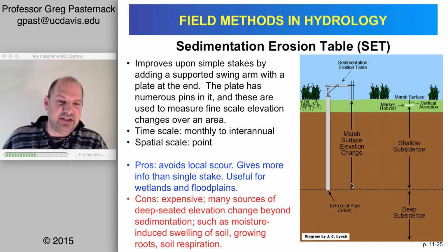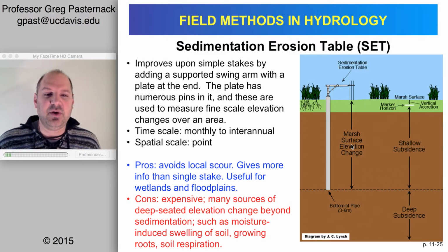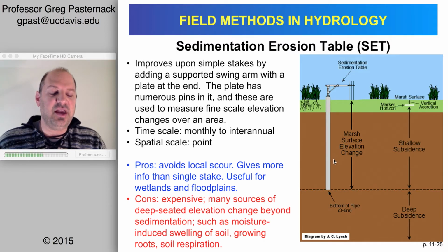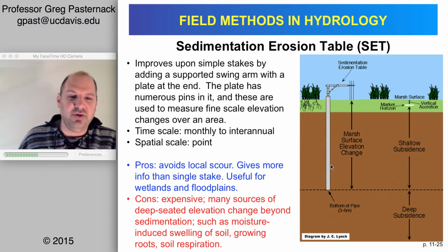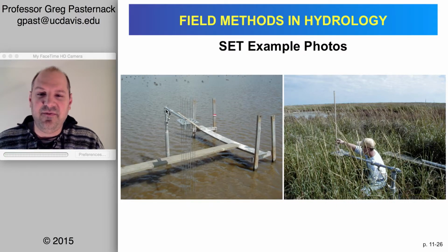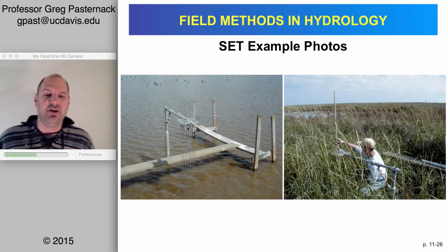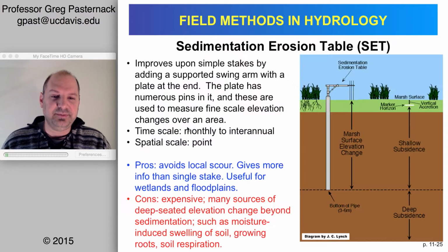Another factor is that, just scientifically, it's measuring change in elevation. And change in elevation isn't just due to erosion and deposition. It's caused also by swelling and shrinking over this full range that is represented. So unless the swelling and shrinking also causes the reference to move, then you don't know. And then, of course, if you're interested in millimeter scale changes, any amount of variability, any flex or pinning in this, just the slightest differences of any kind can cause changes here that would be within the uncertainty that's there.